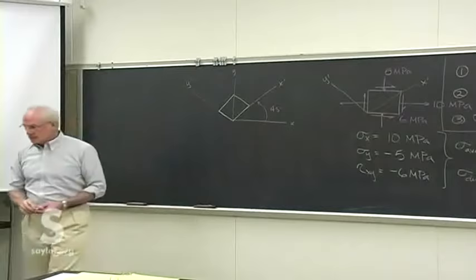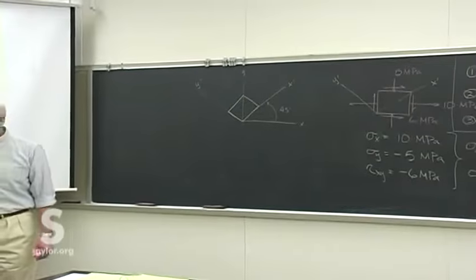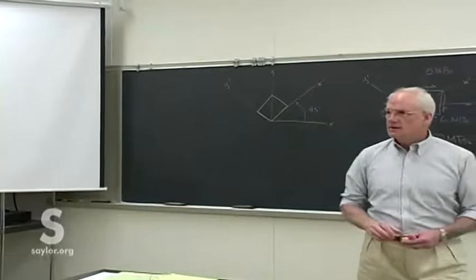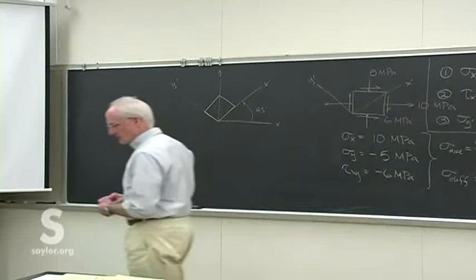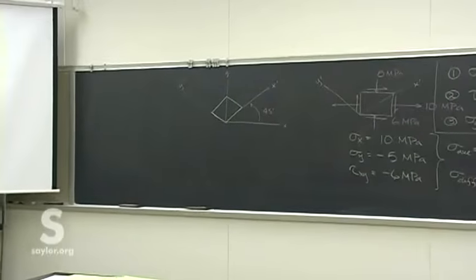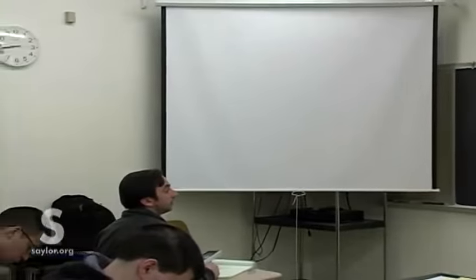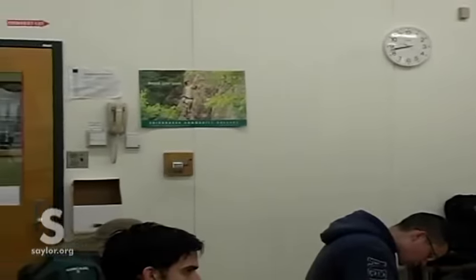So I'll just prepare a new direction, 45 degrees, and we'll figure out what the new stresses are in those new directions. So watch your minus signs. Don't forget the 2 theta. Now, those 1/2 things there. Fix that.